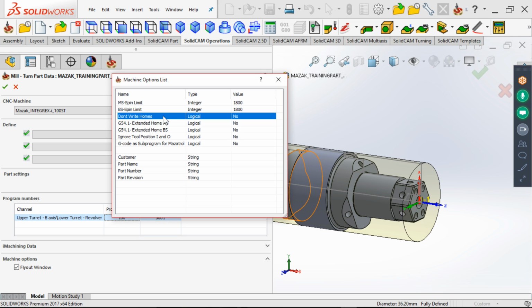This is the old way. Touch the part. If you use yes here, you need to understand that the part transfer then cannot be 100% automatic, and the first part is done. He needs to clamp the part and see maybe 1 millimeter more or less. I don't know. He needs to make some checking also. So the part transfer should also get some corrections, because we don't know where the G54 is. So for now, I like to keep the default as no. So everything will be generated automatically.